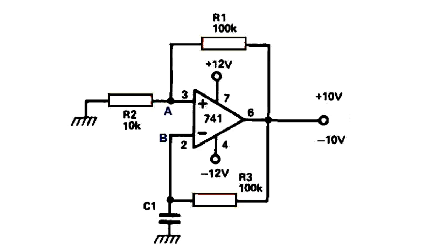The voltage fluctuations on C1 can be used to determine the working frequency of the op-amp oscillator. This is the collapsed portion of an exponential charge-discharge waveform, but we'll disregard it and pretend it's linear, which it almost is.